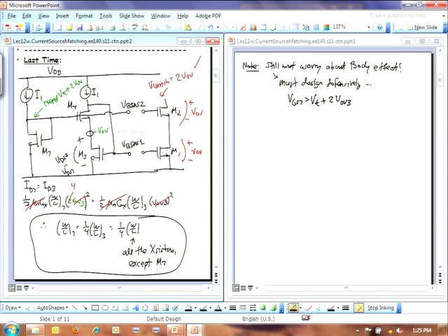So I'm generating a V-bias generator, which is what that is there, just a diode connected device with some current source generator, possibly a resistor doing this, but I'm just going to make it generic and draw a current source there. Okay, and so I'm doing replica biasing to bias up another MOS device that's being used in an actual amplifier. It could be that one. And also to bias up maybe another one here. Call that M1, call that M2.